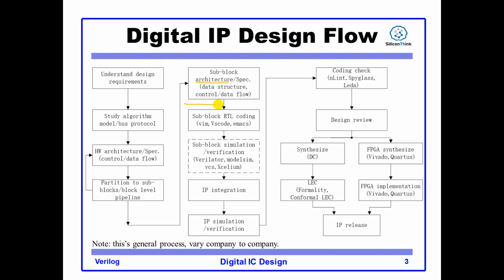In my opinion, all the steps before this line are the most important steps for the whole design process. They are the planning steps. If you dig deeper in these steps, you may have a better life in later stages. For example, if you misunderstand the design requirement, the algorithm, or the bus protocol for this block, all the outcomes of the following stages will be wrong. So these steps are the planning stage, and make sure you are headed in the right direction.